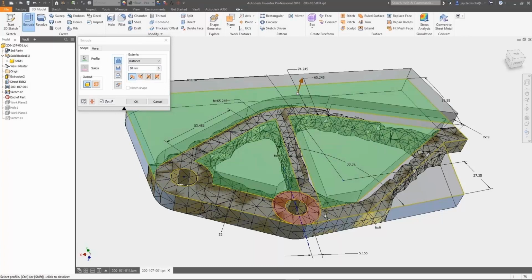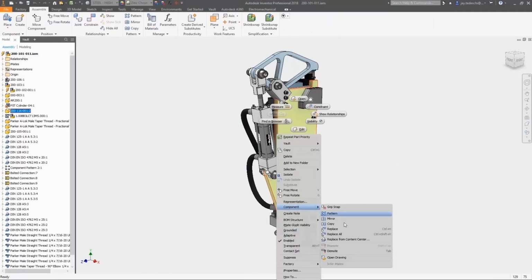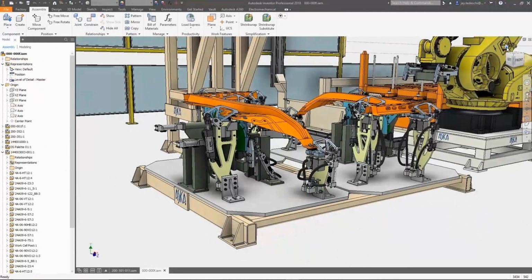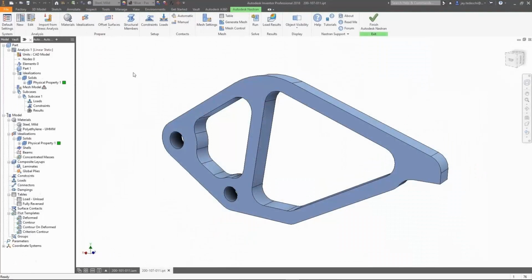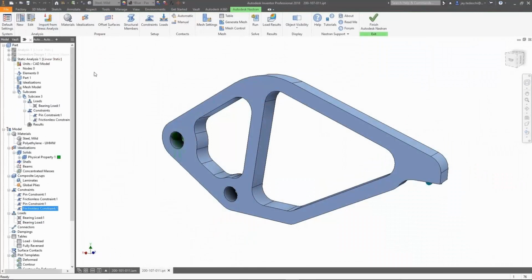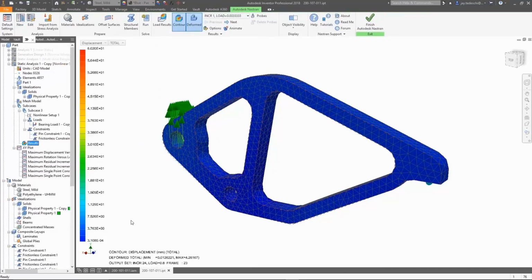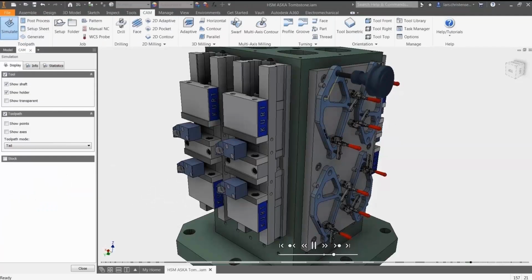Using this as a template, we can then go into our design environment, make changes to the part, and then to verify that, we can bring this back into our overall assembly and check for fits, clearances, and interferences. But more importantly, we can even do structural verification on this. Maybe we're concerned that it might buckle, or maybe we want to investigate various different types of materials to use. We can investigate this using Nastran In-CAD's advanced simulation workflows.